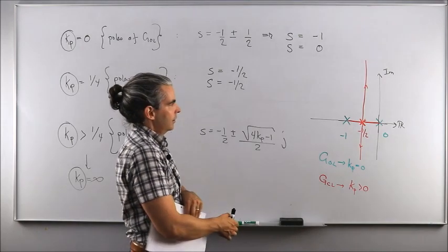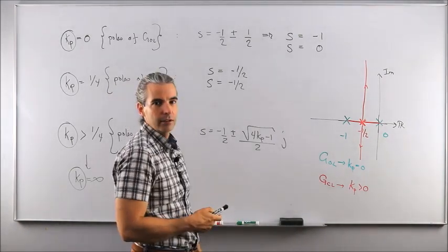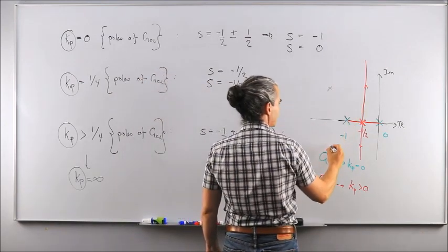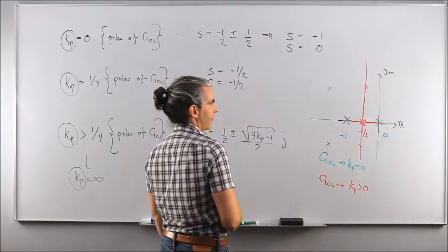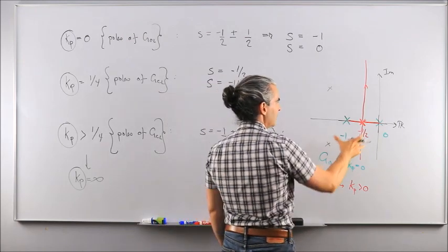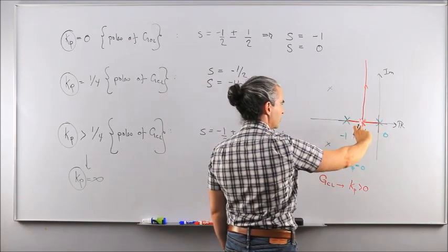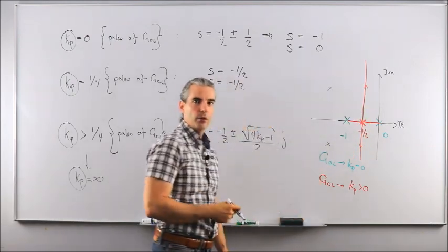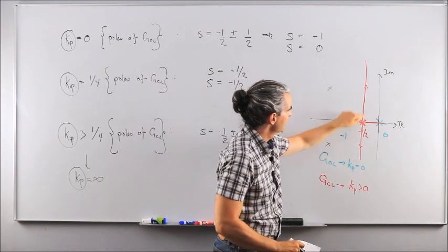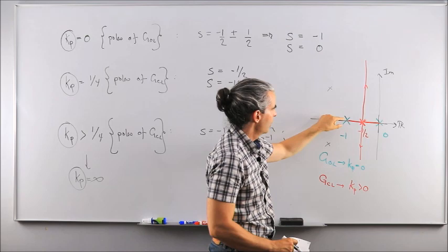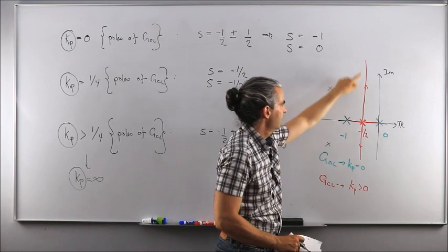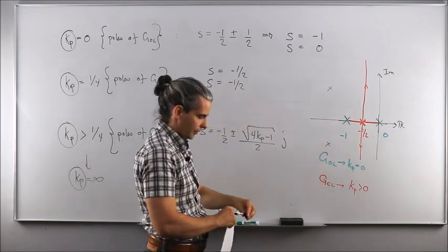So if that is the characteristic you get for the pole locations as a function of Kp, you might say, boy, that doesn't suit my need, because I would really like to have my closed loop poles, say, in this area. But I know that based on the system I have, that would be impossible, because the natural behavior of the pole locations in the complex plane with the controller I have in place is giving me this. So the only allowable positions for my poles in the complex plane are the map I've drawn, right? Or the routes I have drawn here.